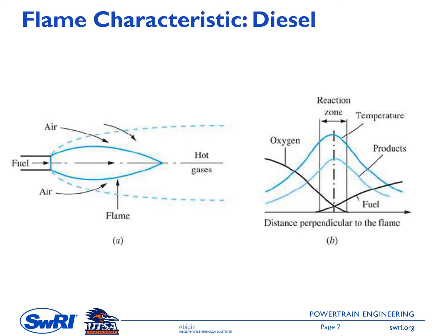In this diffusion flame, the fuel and air are initially separated. In this case, we have a liquid fuel, which is injected through this injector. Then fuel vapor, in this case, is produced within each diesel engine fuel spray. But you don't see it here because we only have one fuel spray here.